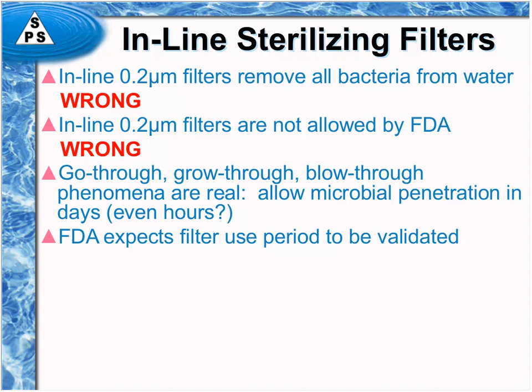In some situations, it could be a matter of hours. In other situations, it could be weeks. But eventually, organisms will get through. So if you ever use a 0.2 micron filter in line in a water system, make sure you have determined how long it takes before organisms get through that filter, because it may be less time than you think.